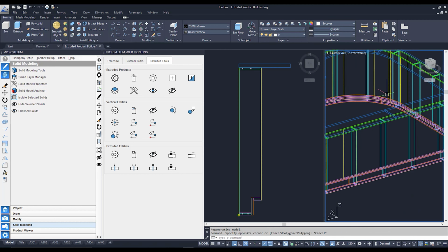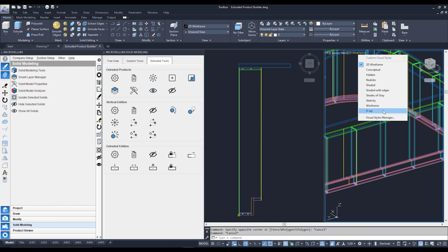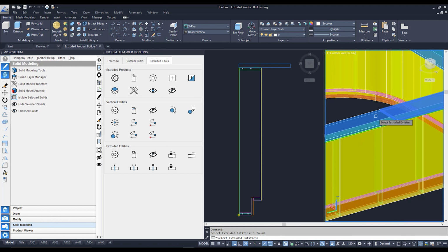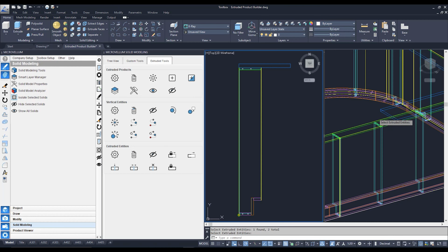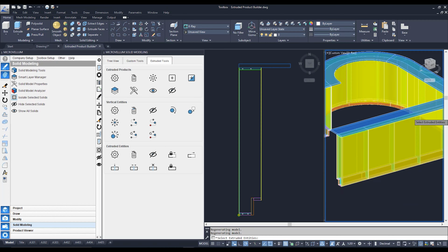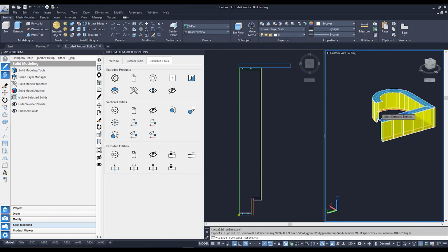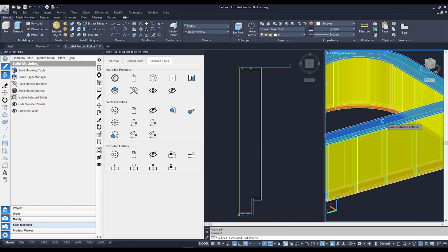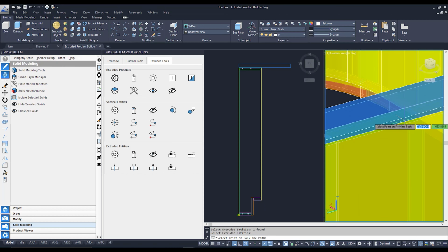So I'm just going to go over to a nice, happy X-ray view, and I'm going to click on this button over here. You want to click on the two entities that are joining together, hit enter, and that join has now disappeared. If I need to add that back in because whoopsie doodle, I can always add another joint in there by clicking on the entity and clicking where I would like it to start.